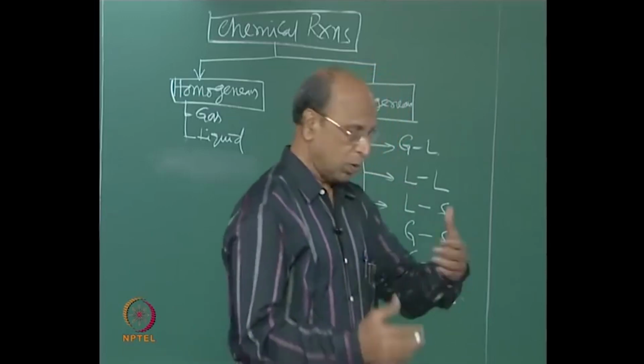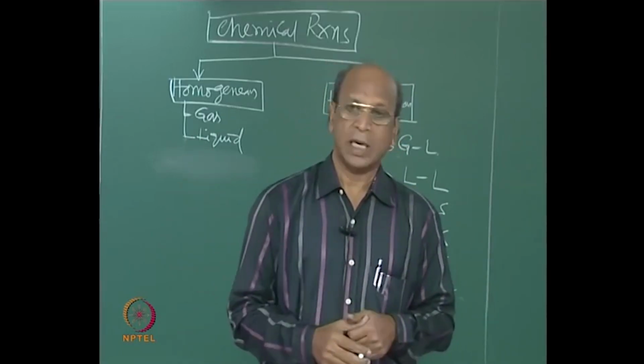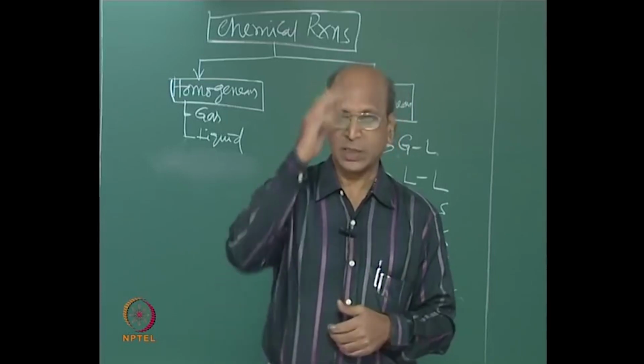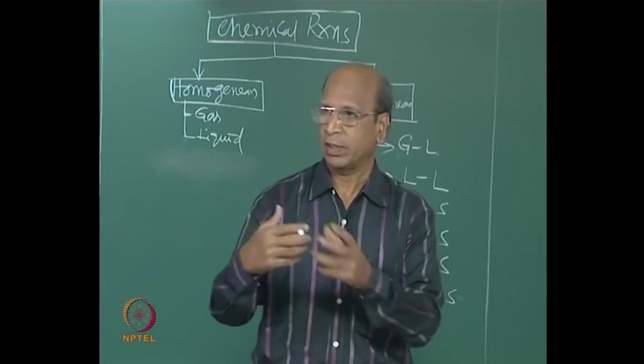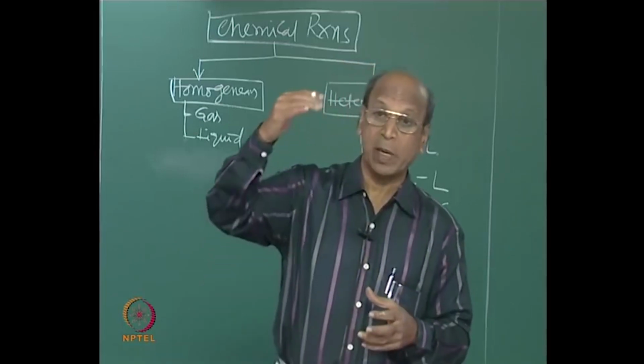So, now this boundary layer is stagnant. Actually, it is not stagnant, it is dynamic, because the oxygen molecules are just diffusing and CO2 molecules are, the oxygen is going in, CO2 also has to come out. That is why you read Fick's law, counter-current diffusion and all that. If exactly 1 mole is going inside and 1 mole is coming outside, then you have equimolar counter diffusion, and if you do not have that, then you have to go for the Stefan equation, for multicomponent diffusion where the mole balance is not proper, all that. So that will become much more complicated.